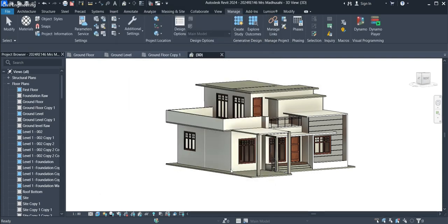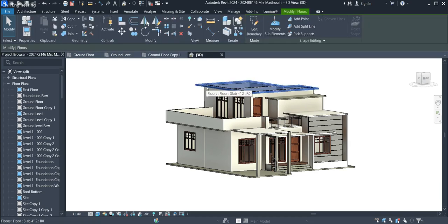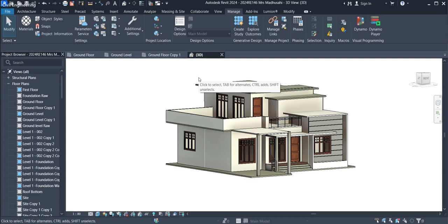Okay, now how can we use these materials in our model? For that, there are two ways. We can get the appearance for architecture purposes by using the paint tool, or we can edit the materials for the newly created material. It means if you need to change this element, floor, into bamboo dark or that wood, we can edit this one into the newly created material.